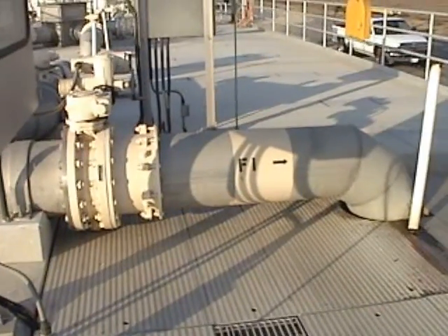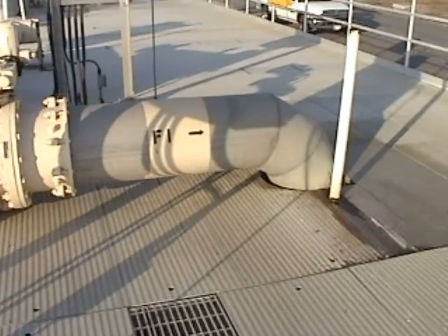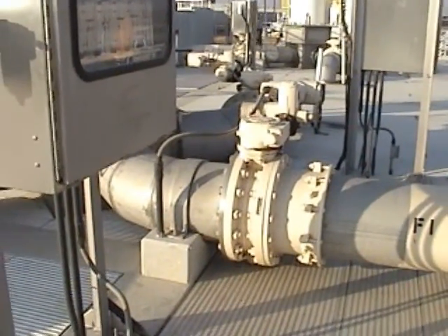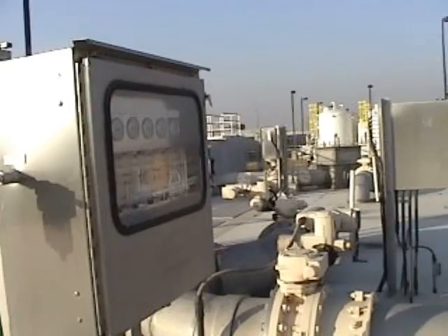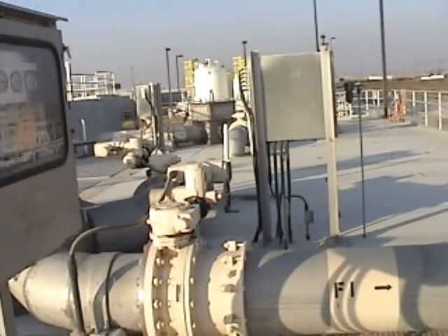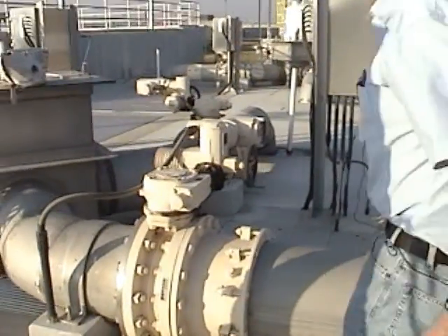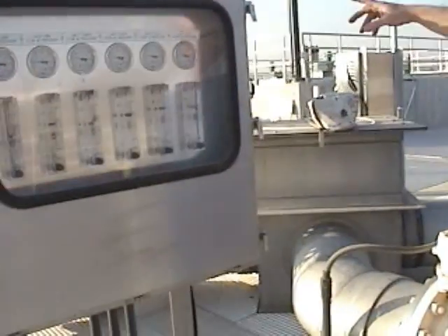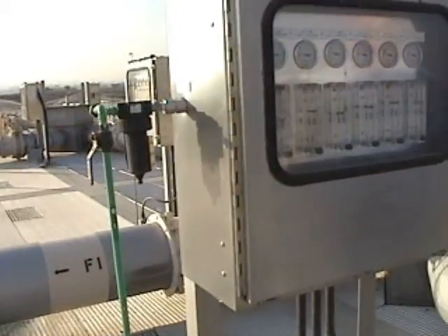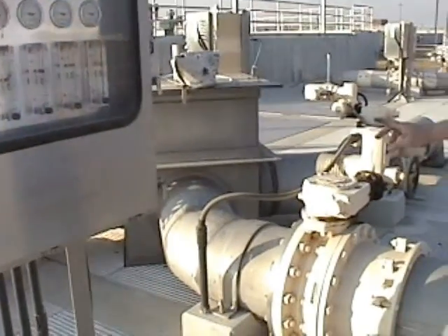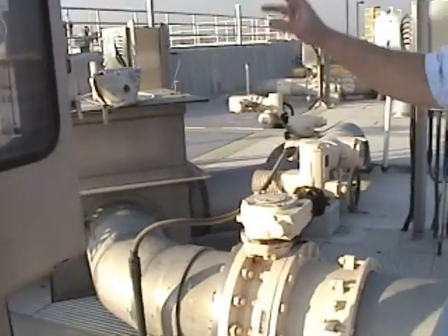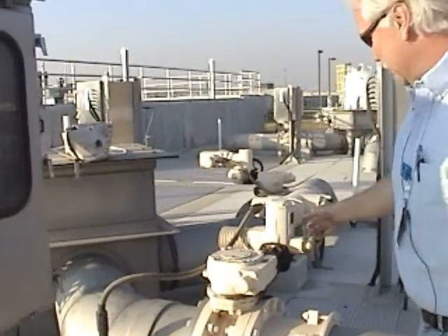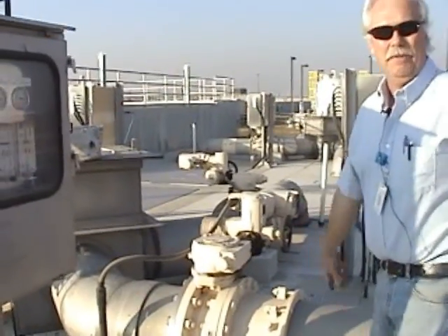Right now what we're doing is we're going through the process. We can't control these by the Foxborough. There's a problem with the electrical system out here. There's noise on the line. So what we have to do when we put them off and on is to open and close the valves by hand. That's probably the best way to do it. You can do it electrically from one of the power centers, but you want to have somebody with you to make sure that when the valve is open or closed, then throw the breaker. If you leave the breaker on, this valve could open or close on its own, all by itself.